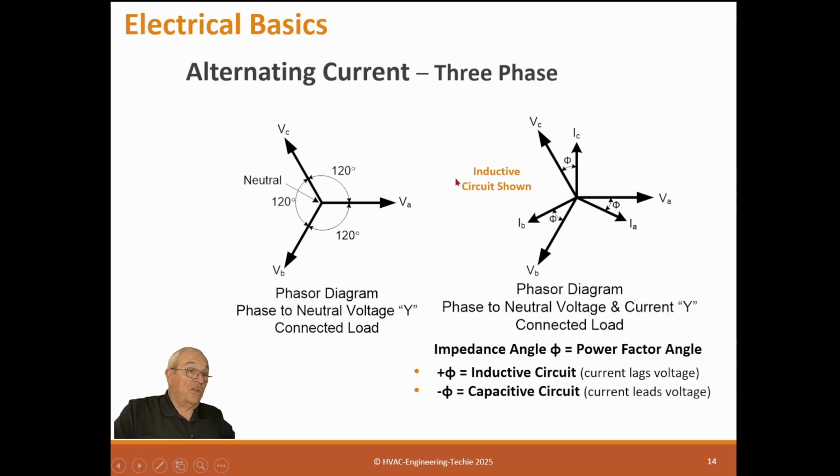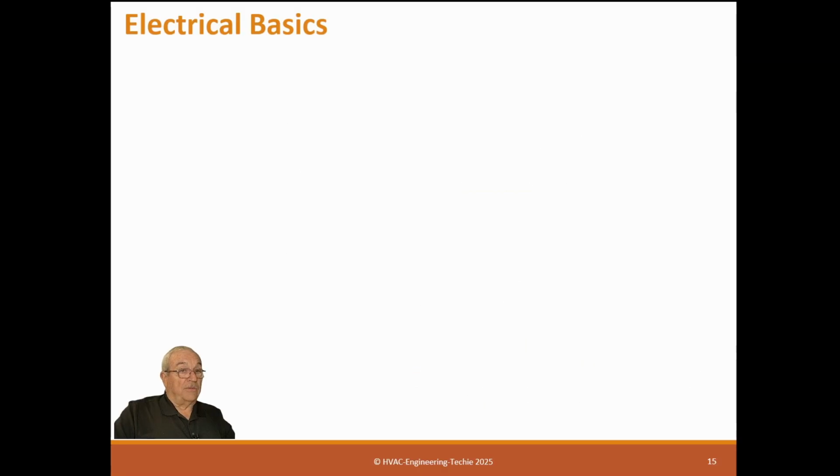Now, the reason this is all important is because you size inductive circuits differently than you size resistive circuits. So it's best to have motor loads and resistive loads separated so you don't mix them up. But if not, you have to use the motor load calculation for everything.